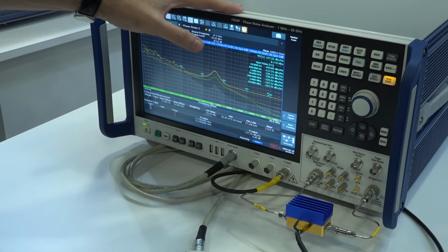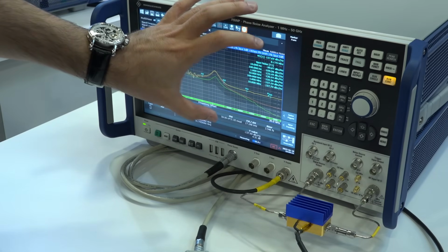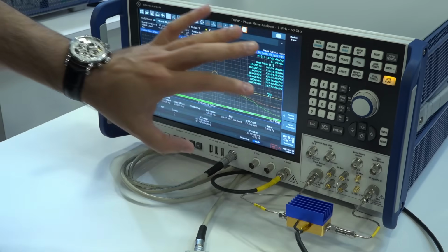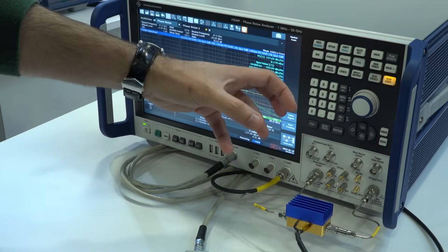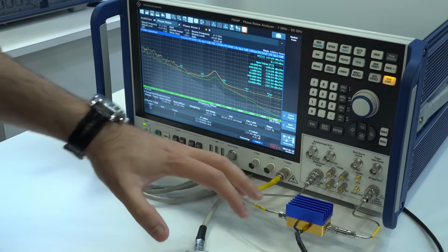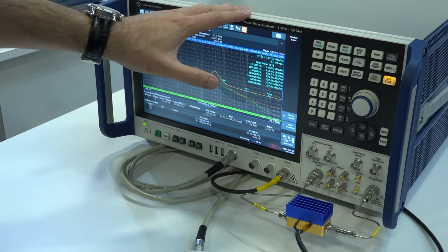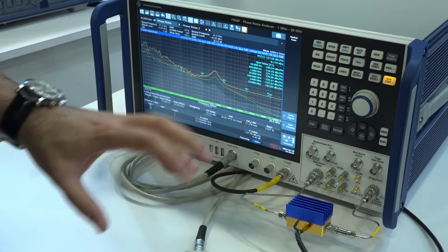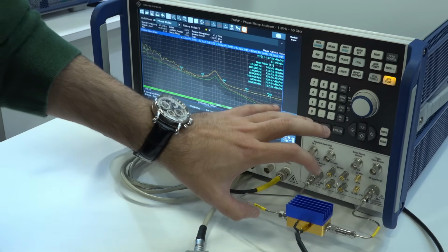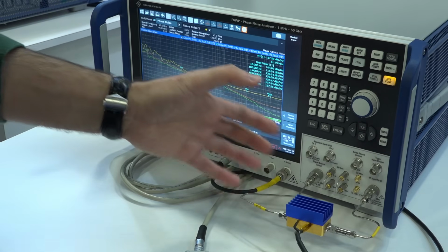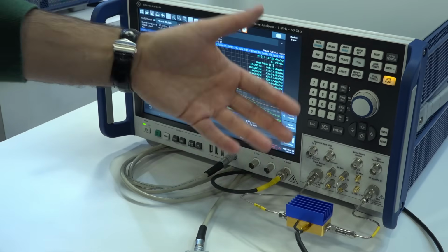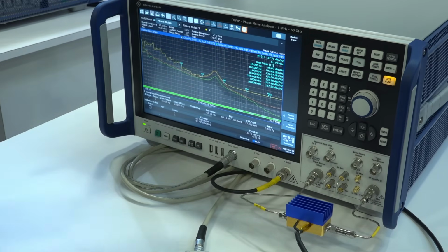Now, one little thing that I wanted to correct here is that the internal sources that go up to 56 gigahertz allow you to do phase noise cross-correlation up to 56 inherently. That's not a problem. The issue is when you want to measure above 54 gigahertz for additive phase noise with external devices, you need to route that signal out of the instrument. And in that situation, you can do it up to 54 gigahertz. That 2 gigahertz difference between them has to do with the amplifiers and the available output power. But nevertheless, having the ability to inject your own external sources gives you flexibility in any case, because in some situations, you want to get increased speed, or you want to reduce the number of measurements you want to make to get to the cross-correlation floor, and that still allows you to do that.